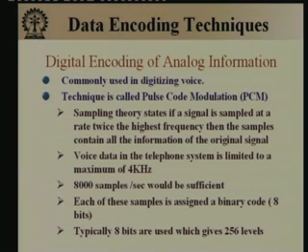So, if we have 4 kilohertz of bandwidth, we require 8000 samples per second. That means per second, for this analog voice, we will take 8000 sample values at different points, all right. Of course, at some point my voice may be low, so I may have a very small amplitude. At some point my voice may be very high, so I can have a large amplitude. So, we have such 8000 samples.